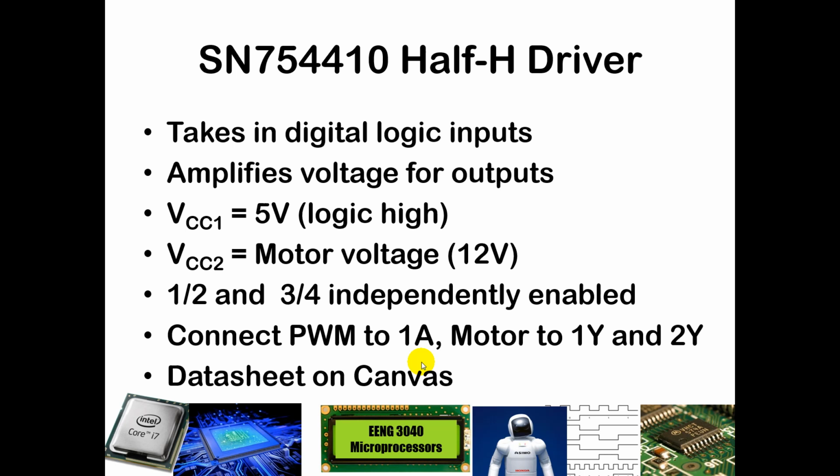We are going to be using the SN754410 half H driver. What that will do is take in digital logic inputs and amplify it to the voltages necessary to control the motor. Our PIC can only output up to 5 volts. That will be the 5 volt PWM signal, but we need a 12 volt PWM to control our 12 volt DC motor. And so we will input for VCC1 a 5 volt logic high.